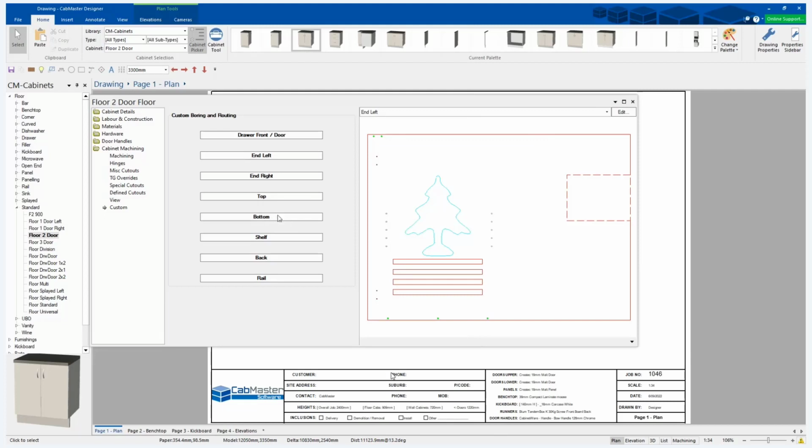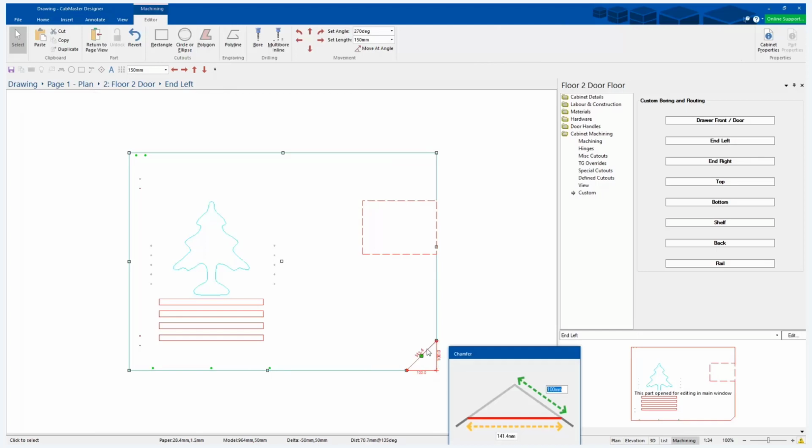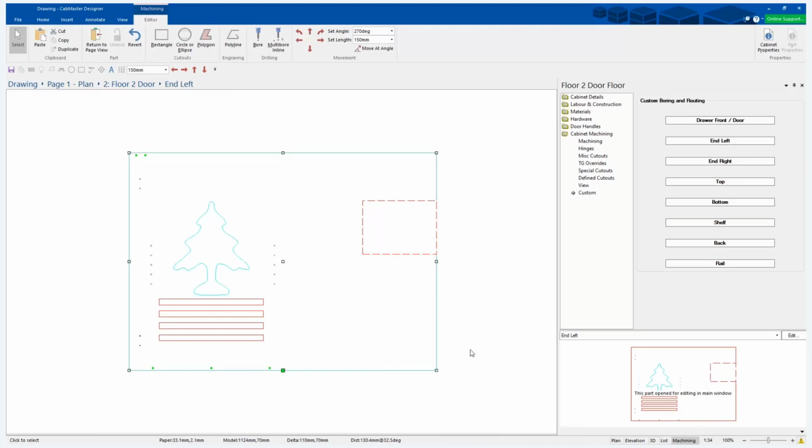So can you fillet chamfer angles at other than 45 degrees? Again, yes and no. A chamfer, no. If you chamfer a corner, no, you can't. But again, there's other ways to do things. You go add a corner, and add a corner to there, and I can add a corner to here, and you can specify where the corner actually is and how far it is, and then I can chamfer, and I can actually delete this corner here. And now I have something that's not 45 degrees.